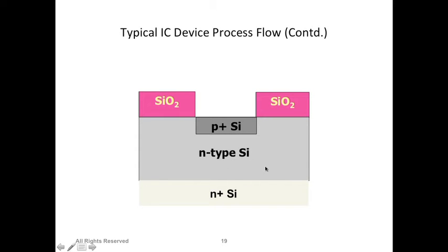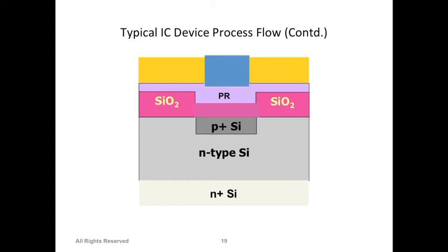And then the next step is, okay, sorry, what is this? Okay, we put a photoresist. Then we put a mask. It will open up certain areas in there. Then we remove that. I think purple is the photoresist. Then you etch the silicon dioxide.